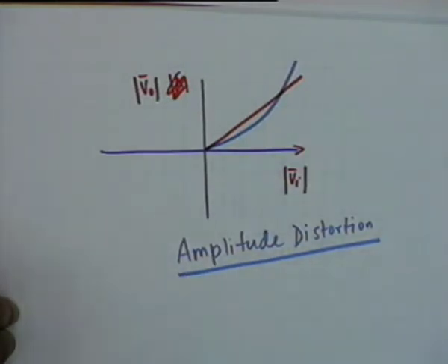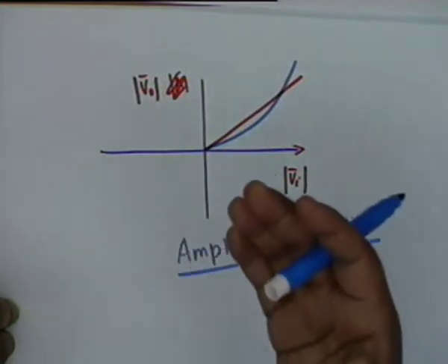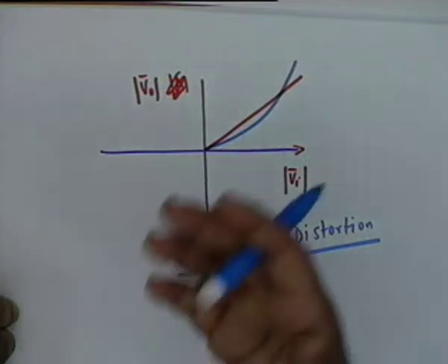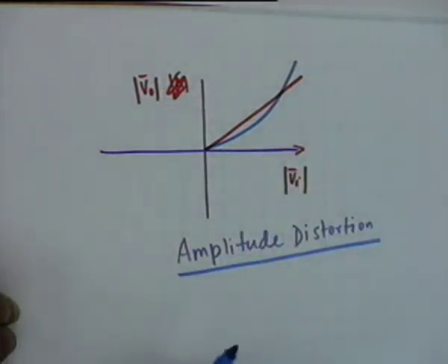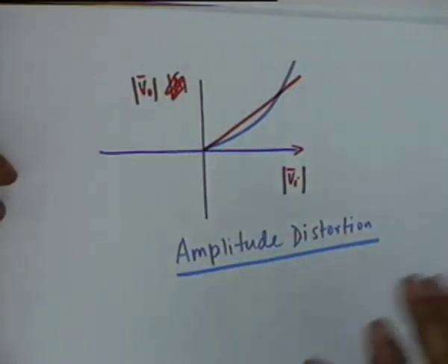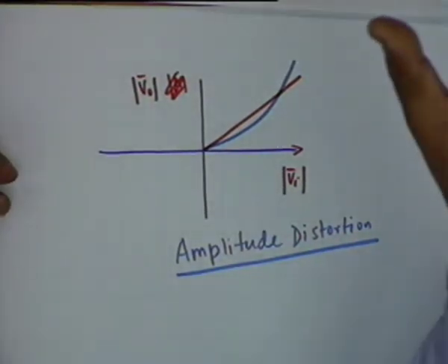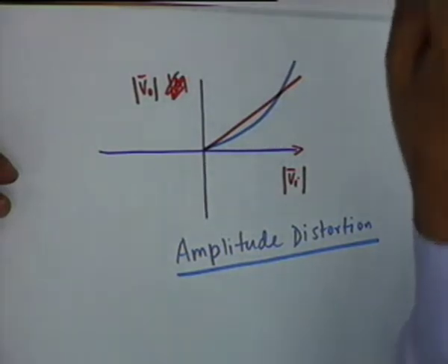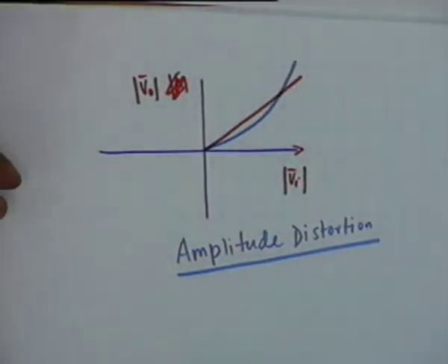For musical reproduction, we require a very, very good linearity of amplification. On the other hand, speech, most of it is not paid attention to, so somebody speaks, that's about it. And there is a large crowd, okay? I'll say TV news. The actual content of the speech is not important, and therefore a lot of amplitude distortion is tolerated in a public address system. It cannot be tolerated in music.